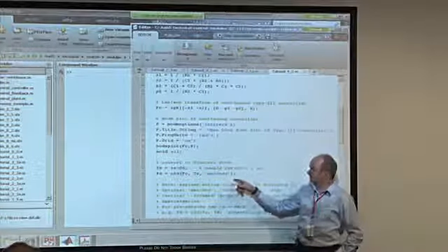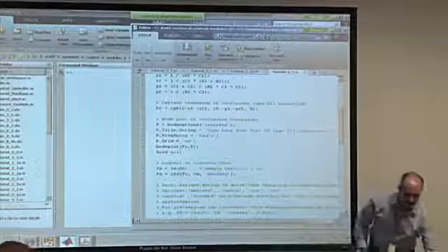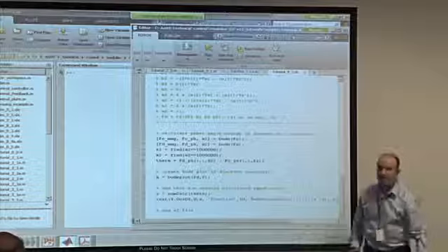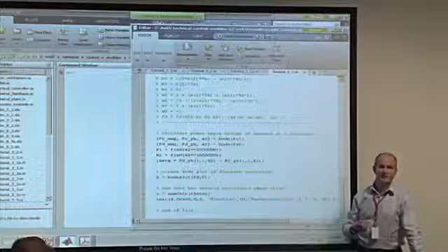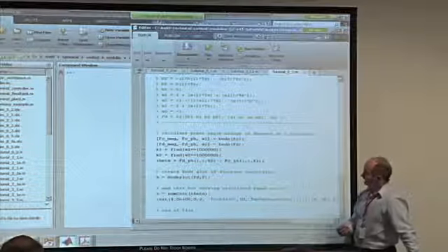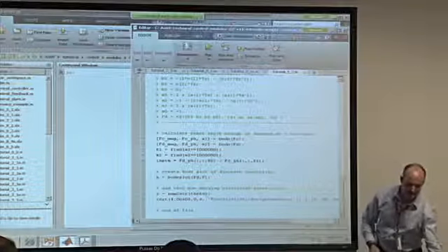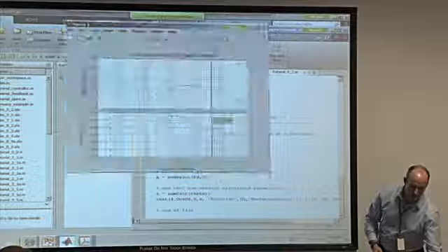I've just described. A little bit further down at the bottom, there are some lines which measure the phase response, because it's principally the phase response which is in error when you do this. And I'm going to pick out the phase response at 1 times 10 to the 6 radians per second. Let me run it, and it'll be clearer.